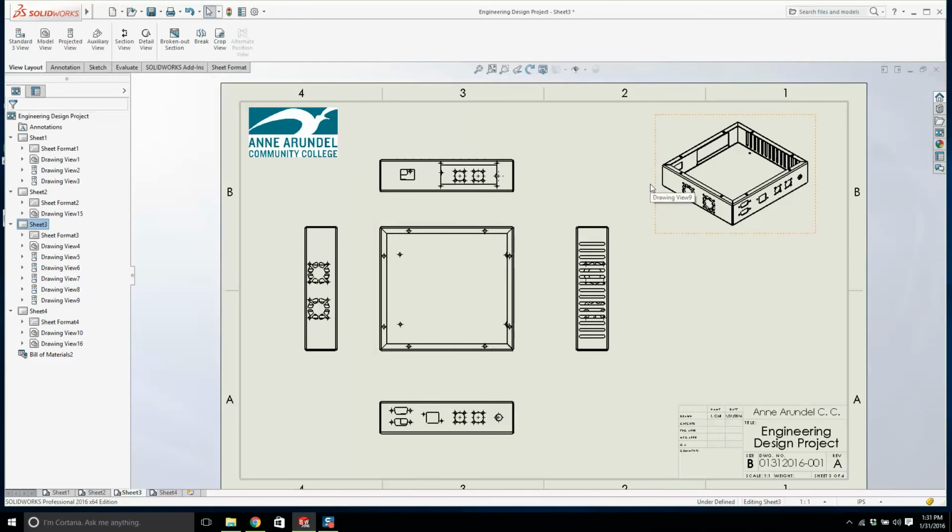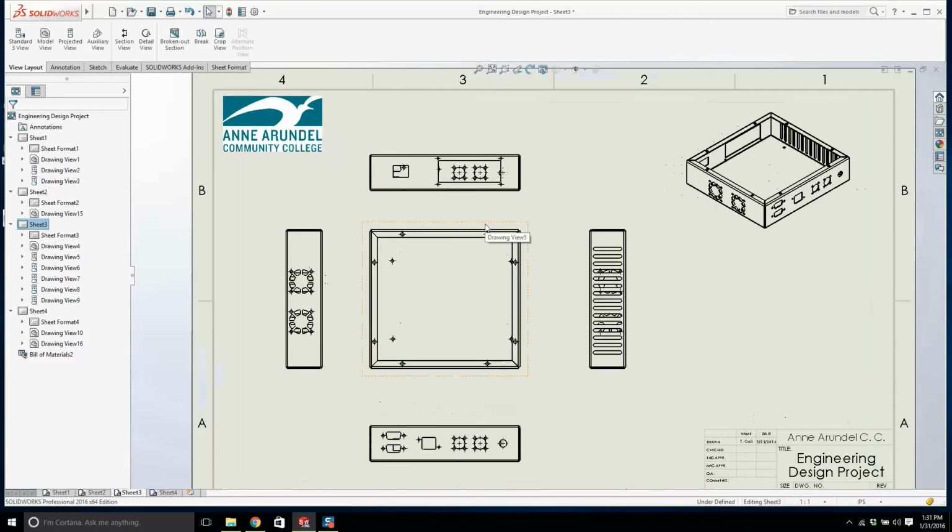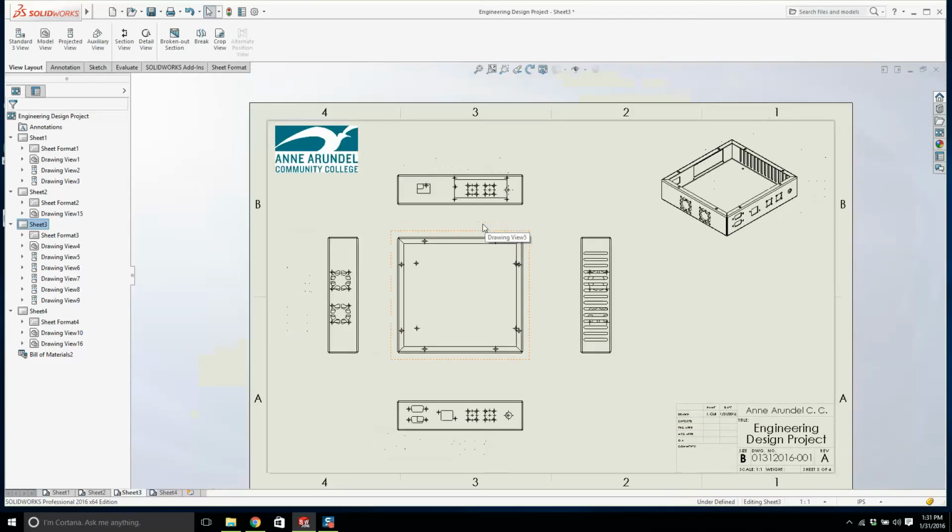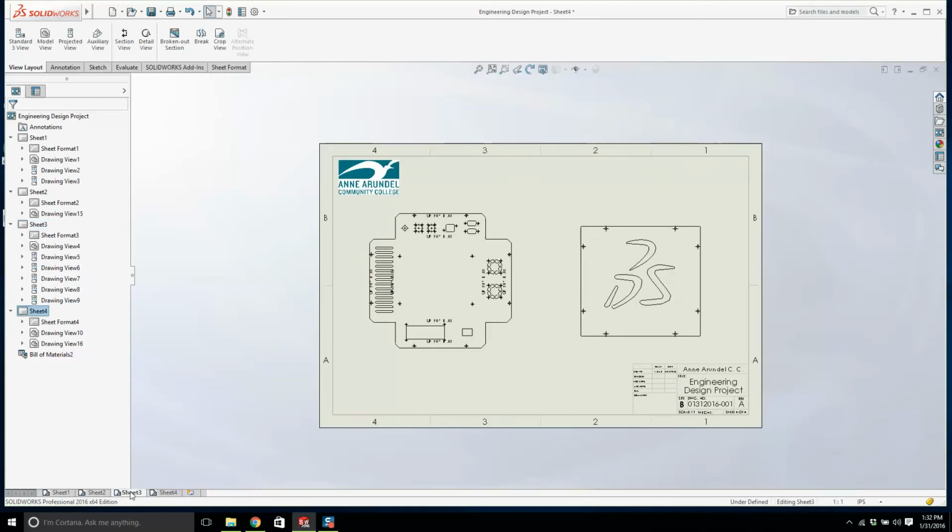Now, when you're creating this assembly, I don't want you to model this sheet metal enclosure up based on the dimensions that you get here. I want you to set up the components where they should be, and then build the sheet metal around the components. I want you to do an assembly driven design. Do you know what I'm saying? Now some of you, if you're having a major issue with the assembly driven design, try it again. Just only as a backup are you able to draw this sheet metal based on this drawing. Make sure you're very clear on that. I want you to have some concept of an assembly driven design. That's what you're going to be doing. That's the point I wanted to make.